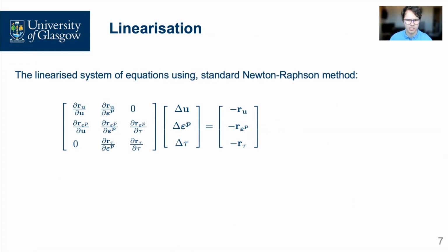So linearization of the system for Newton method in this case is rather straightforward. Note that we only have to compute the partial derivatives of our residual expressions for all three governing equations for displacement, plastic multiplier, and plastic strains.